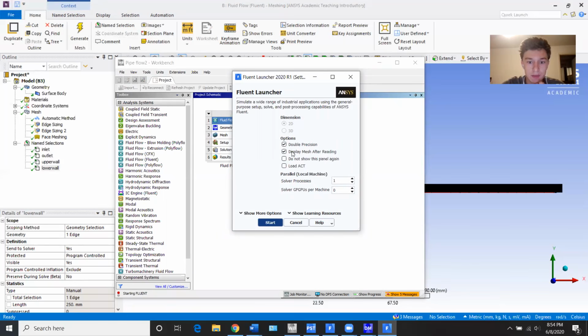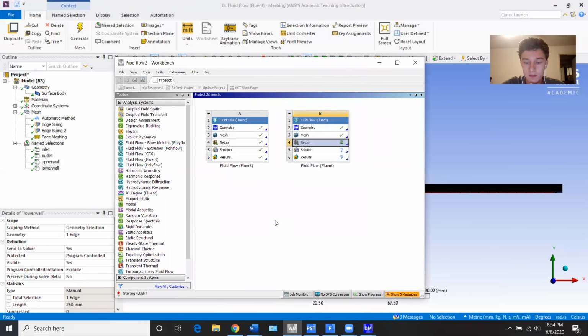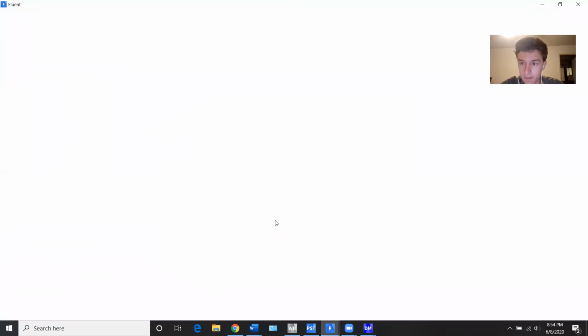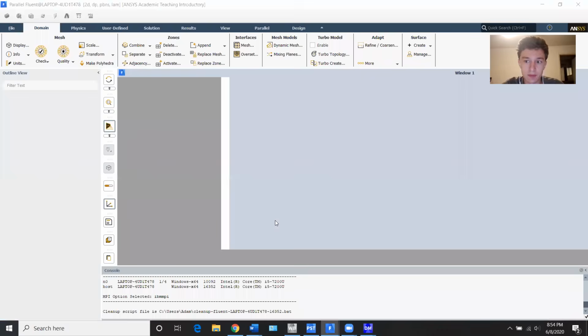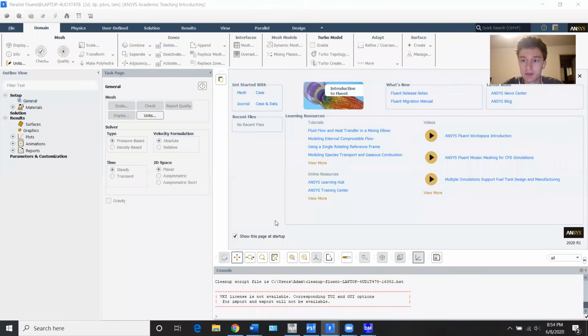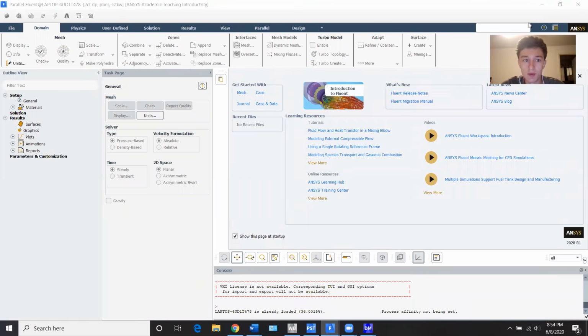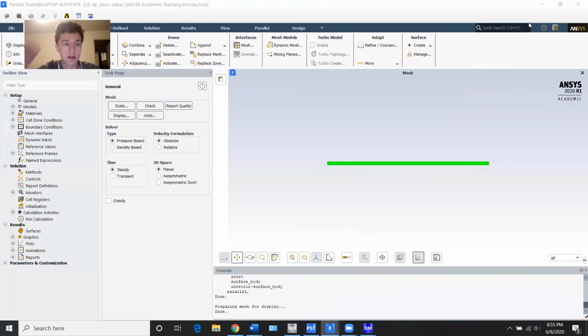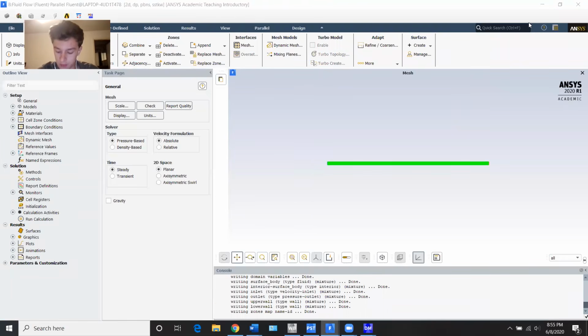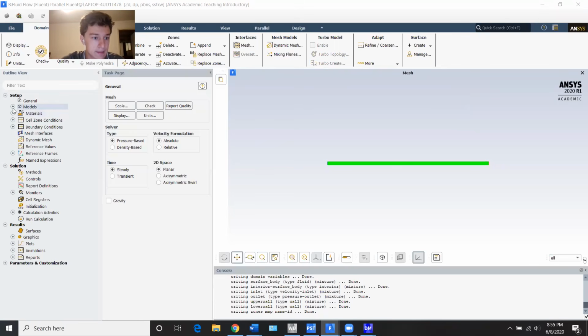We'll just click double precision for Fluent, and let's start it up. So this is where you kind of have to play with the values, mostly with the viscosity, because depending on if it's too high or too low, you'll either not see anything, or else it'll develop too quickly and you won't be able to see any difference between the midpoint and the endpoint. So through a lot of trial and error, I figured out the values that work well for the Poiseuille and the Couette.